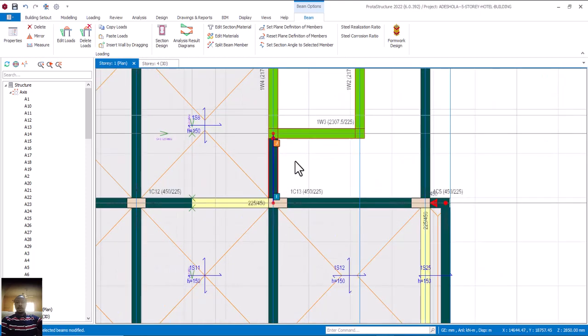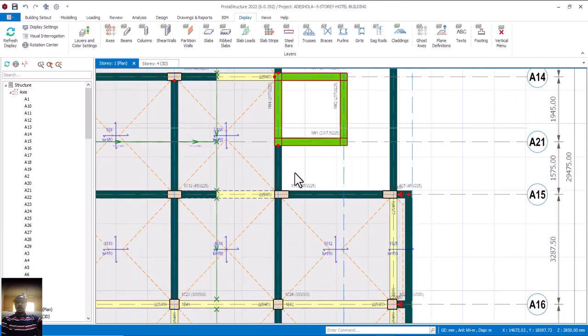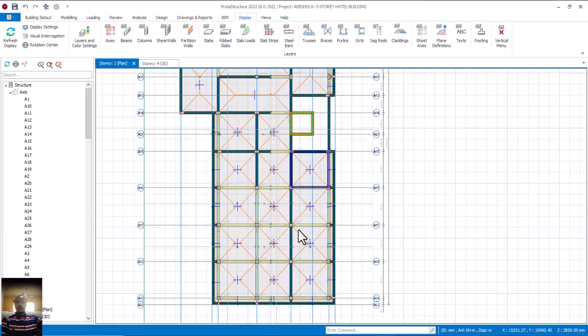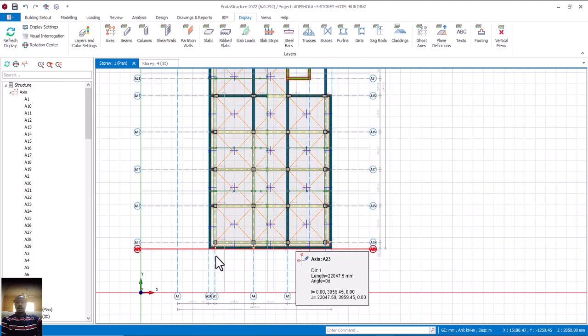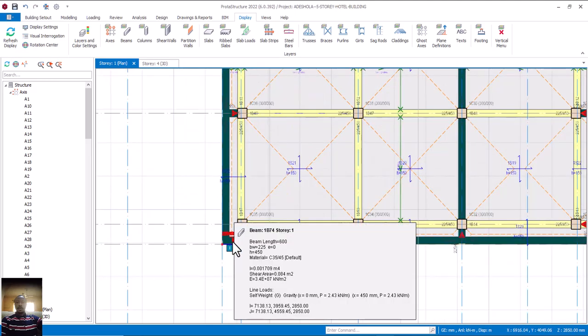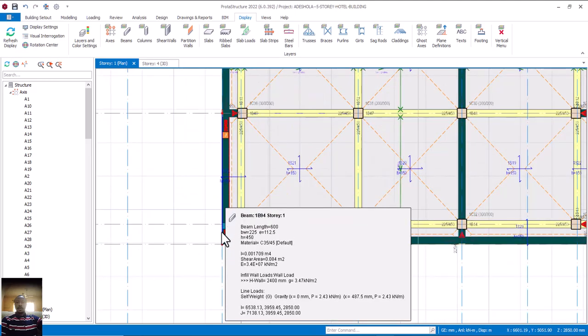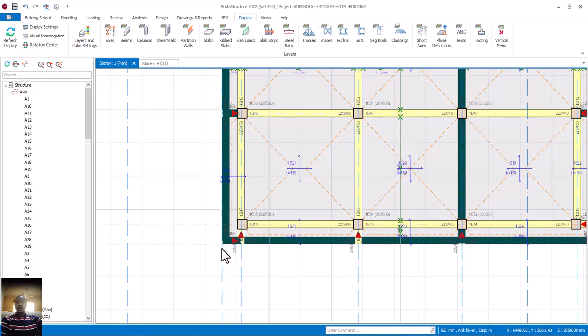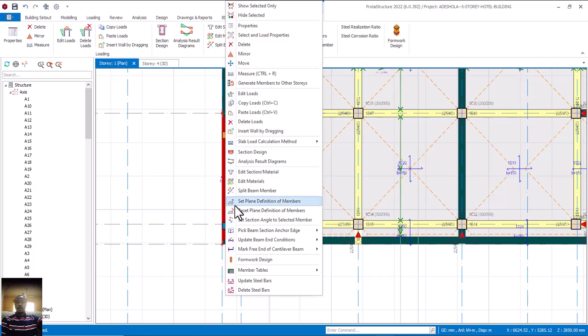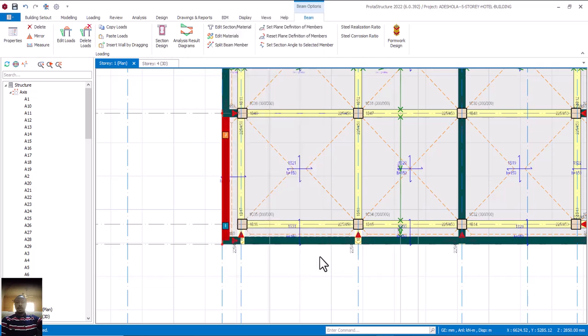Okay, that's done. It's there already. Okay, let's look for other ones. On this other side, you see this cantilever. I'm not going to hinge it, but this one I'm going to hinge. Why? Because on this other side there's no continuation. Is that okay? So I'll click on this one, which is the I side. I then click on this, come to this place and click on I. I click on apply. Is that okay? So that is that.